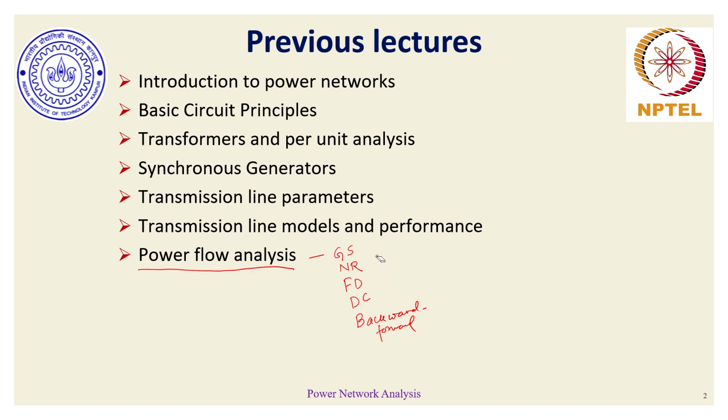Before I go further, I have probably not explained something clearly about the DC model. If you recollect the DC power flow lecture discussion, therein our bus voltage phase angles theta were expressed in terms of an X matrix, which was multiplied with the power injections at all buses except the slack bus. This vector equation was not applicable for the slack bus, because for the slack bus the phase angle reference is already known or defined.